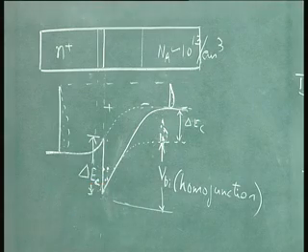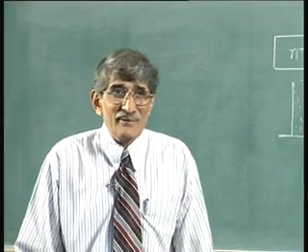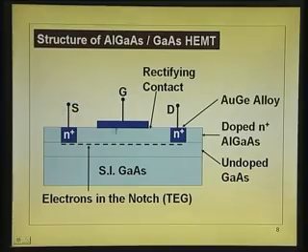So, the current will be controlled by the top layer. This is the layer which will control the current. In the sense, entire transport will be controlled by this. So, you will have low mobility effect. So, put a gate here so that you can deplete the entire layer. Okay. I will come back to those more details after. Right now, I will keep you in the perspective how you are avoiding that current transport through that.